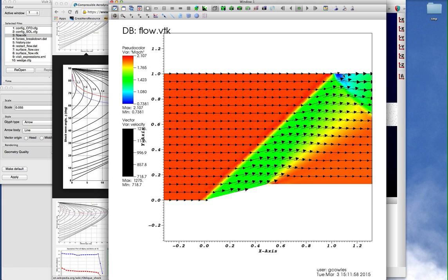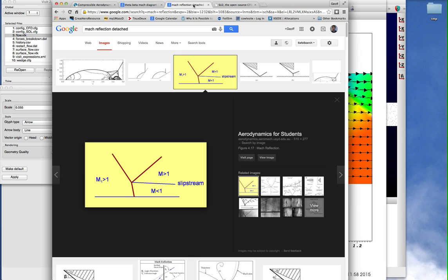So there isn't a solution for an oblique shock that can turn the flow back 15 degrees from this Mach number. So what you get, and it's not well represented here, is what's called a Mach reflection. You can see that there's a big drop in the Mach number here, and you have this region of subsonic flow. This blue region is subsonic flow. You have subsonic flow here. So essentially what's here is a normal shock. And let me show you what you're seeing. It's not well resolved here.